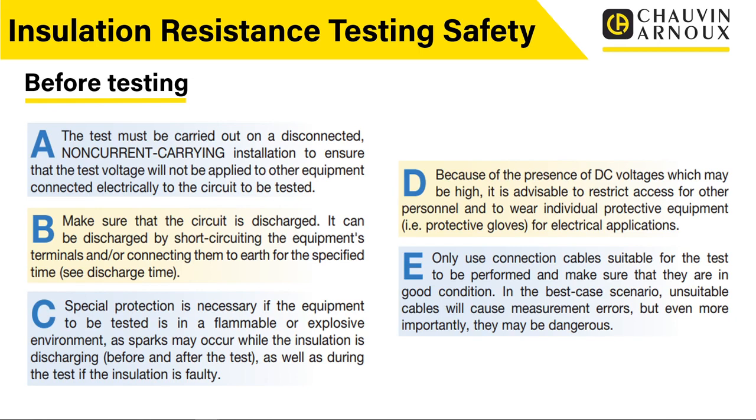We're connecting up, we're testing at one end of the cable. There could be somebody connected, leaning on something at the other end, or especially if we're testing to earth parts, we could actually be applying that voltage to any earth part within the premises. So somebody could be touching a water pipe, somebody could be touching a tap, somebody could be in a bath, and we're carrying out this test. Obviously, we run the risk of giving people electric shocks.